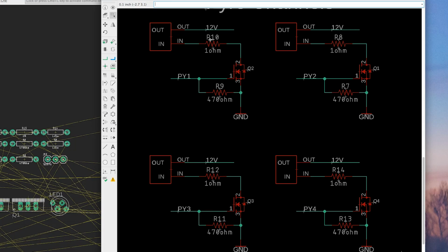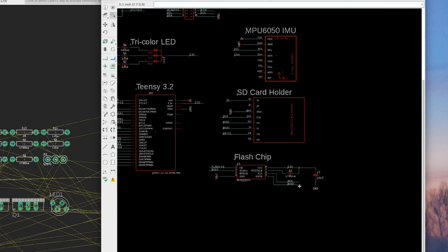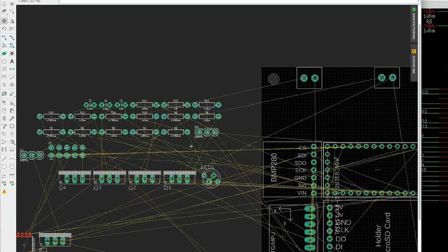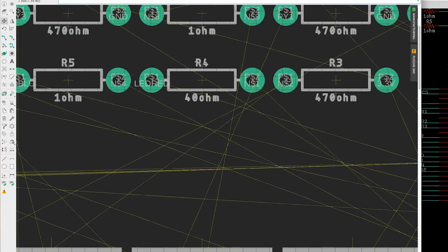What you'll notice is that there are specific designators on each component here. This resistor is R10, this resistor is R14. If we go over, let's find a capacitor. This capacitor is C5. Each part of the board has a designator associated with it, and this is really going to help you go through and design your board. So look, here are all of our Qs. Each resistor has R4, R3, R5. This is how I'm able to know which part corresponds to which other part on the board.